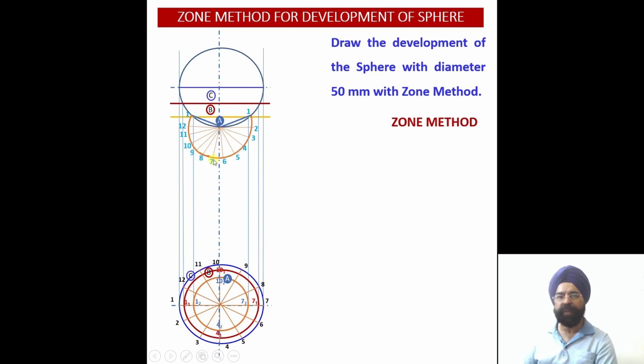So this gives me, you see, if I just join this, this gives me the development of the first portion, first segment, which was sliced over there. So the first segment, I have assumed it as per the approximation method that it behaves like a cone. So the development of the smallest cone, which is having very low altitude value, has been done over here. Now second, you see, this is the second slice.